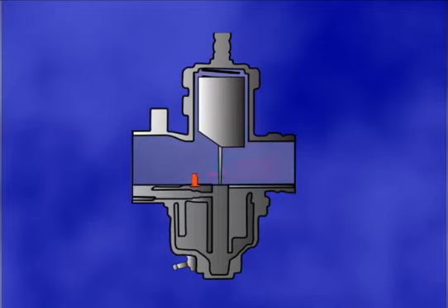This is necessary because when the throttle is opened suddenly, vacuum drops in the venturi, causing a momentary reduction of fuel flow through the needle and main jets. This lean condition could cause the engine to hesitate or stumble. For further information on accelerator pump circuits, consult the video reference manual.